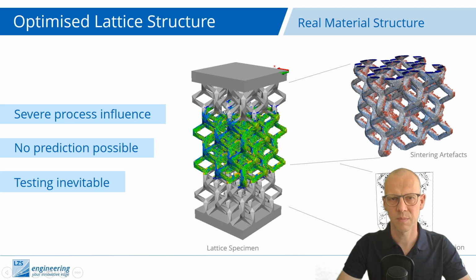And especially in the powder-based technologies, you have two problems. The first problem is voids, so it means you have small air gaps between your metal powder, and during the melting by laser or other technologies, these voids do not go away. You still have gaps in your materials.